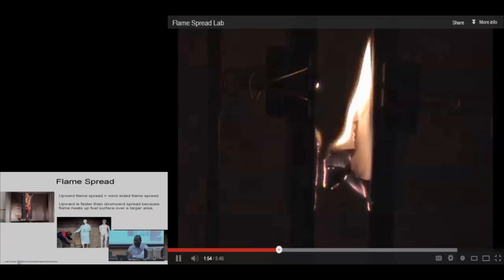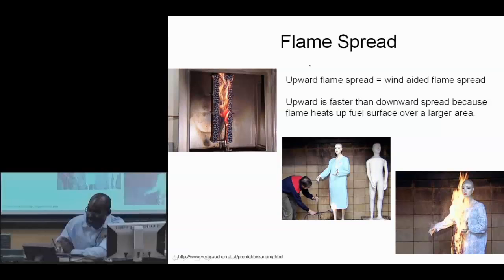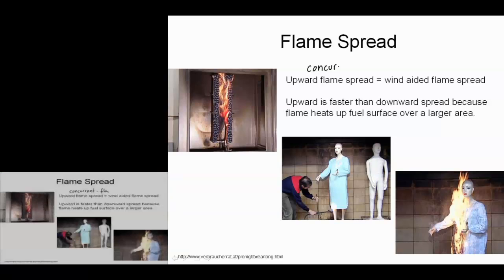Absolutely. And we already have most of the tools to be able to do that because of what we did with the solid ignition problems. So we already said pieces of this. We said upward flame spread is also sometimes called wind-aided flame spread. It's also sometimes called concurrent flow flame spread. And the upward flow is faster than downward spread because the flame heats up the fuel surface over a